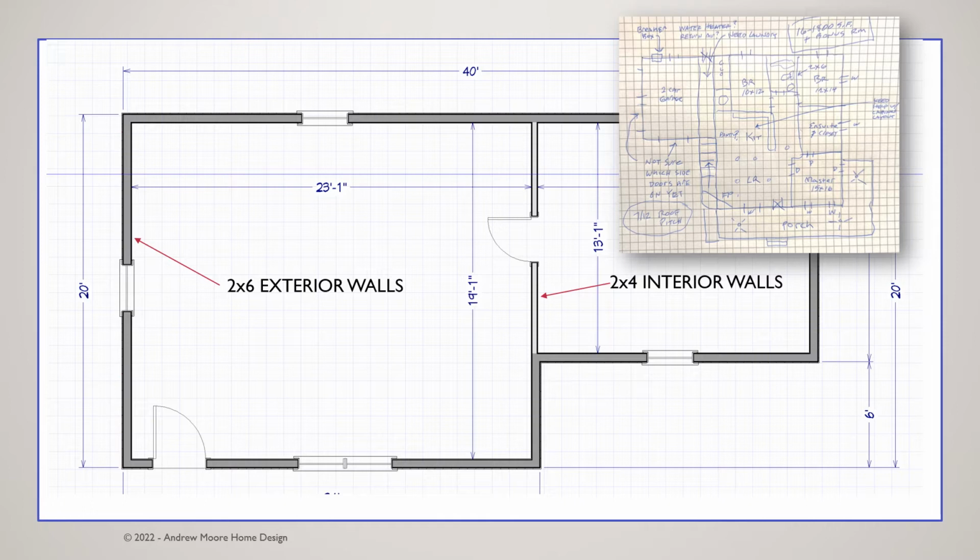You don't have to actually draw in the wall thickness when you do your sketching, but you need to realize that a 20x40 building does not equal a 20x40 room. You'd have to subtract the actual wall thicknesses from the outer foundation dimensions to know the actual room dimensions. When you sketch a floor plan without considering wall thicknesses, that error adds up across the length or width of the house, making the actual space available less than what you might desire. I hope that makes sense. But that is the number one mistake people make when drawing sketches, even when using graph paper.